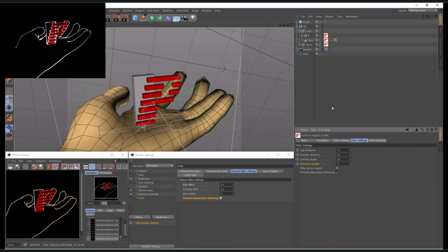So, for example, let's increase the gap distance to 10, and you see already a significant reduction of points. Anyhow, there's one weird line over there that should not be here. And I will, I think, change this back to roughly 5 and a little bit less. And as you see, so there are several features to play around with, and you really need to check the result in real time, as I did now. So I will paste back to 10 and check again.